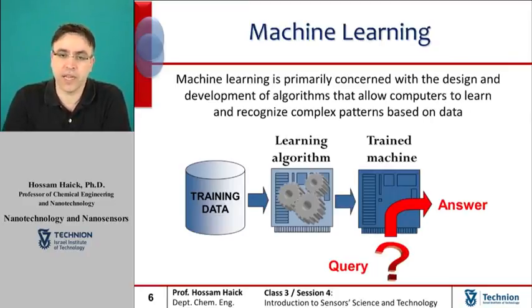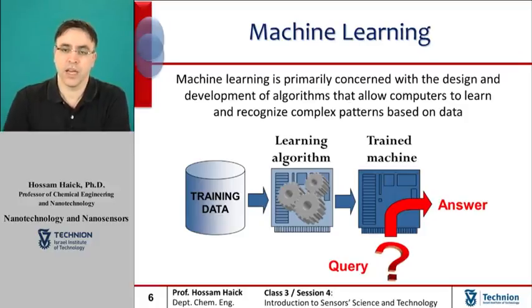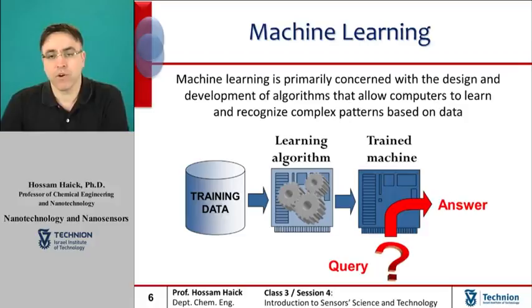After the sensors of an electronic nose are in place, an algorithm must analyze the responses of the sensors. As a first step, an electronic nose needs to be trained with qualified samples so as to build a database of reference. Then, the instrument can recognize new samples by comparing volatile or non-volatile compounds' fingerprint to those contained in its database. Thus, they can perform qualitative or quantitative analysis.